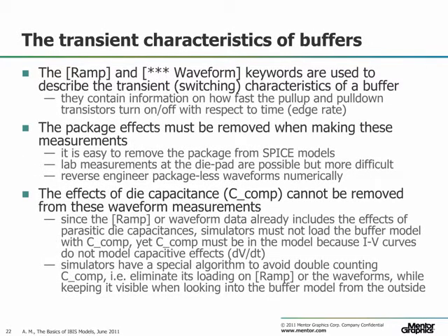The transient or switching characteristics of buffers are described by the ramp or the various waveform keywords in the IBIS file. The package effects should not be included in the data which are made for these keywords. This is easily done in SPICE because we can just delete the package model from our simulations and record the data that way. This might be a lot harder to achieve in actual lab measurements, but there are numerical methods which can be used to de-embed the package effects in those waveforms.